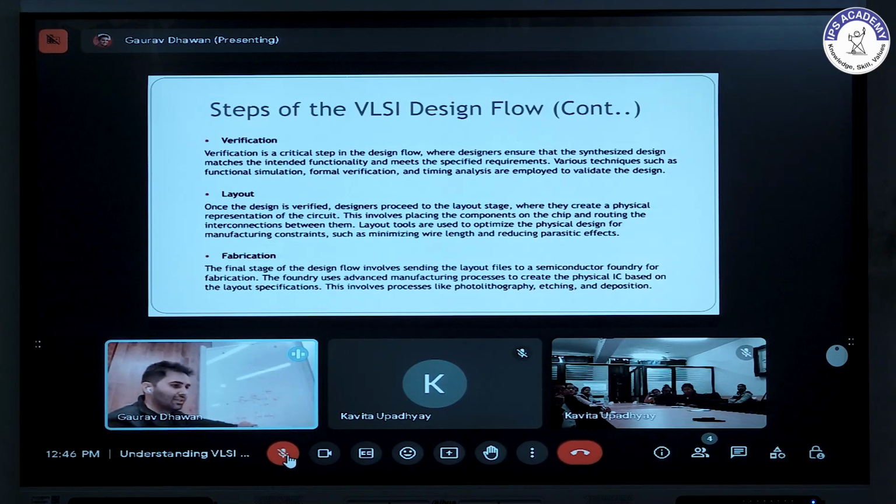So when we say timing analysis, what the tool will do is this: this is your original circuit. But let's say after the synthesis, the design has been optimized, and the tool removes these two inverters. After the optimization, what is the new delay? The new delay becomes 10 nanosecond. So of course there is a change in timing. Whether this 10 nanosecond can give you proper data or not is what is checked by the timing analysis tool, to check whether the timing has been met or not. This is what we call timing.